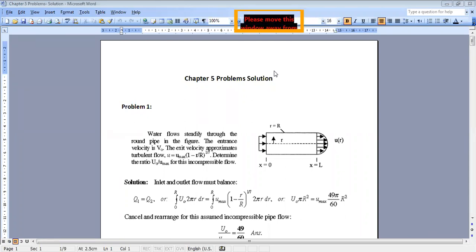The first application of this Reynolds transport theorem is to set B equal to 1. And when you set B equal to 1 and replace in the Reynolds transport theorem, you get the continuity equation. The second application is to replace B by V, and then you will obtain the force balance equation. And at the end, if you replace by energy, you will get the second law of thermodynamics. So let us start with the first application of Reynolds transport theorem, which is the continuity equation.